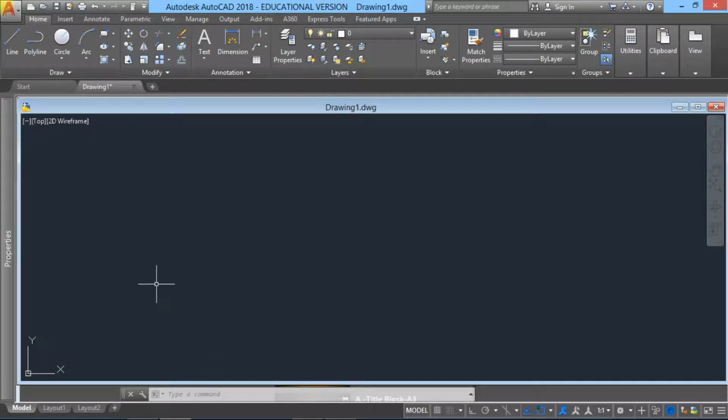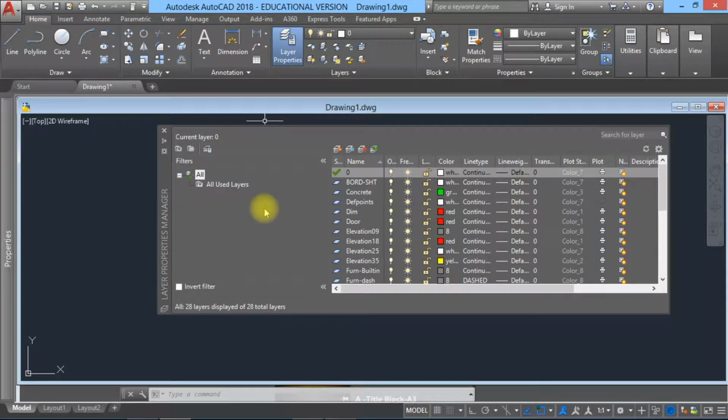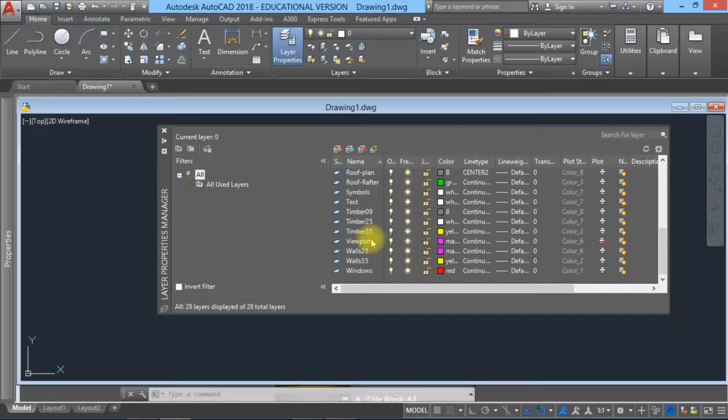Second step would be your layer setups. According to page 5, you have a table of your layers that I hope you will put a little time into to set up your layers. Within these layers, you can see that just your viewport layer is not printable.